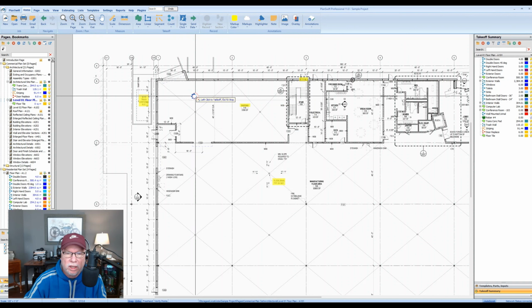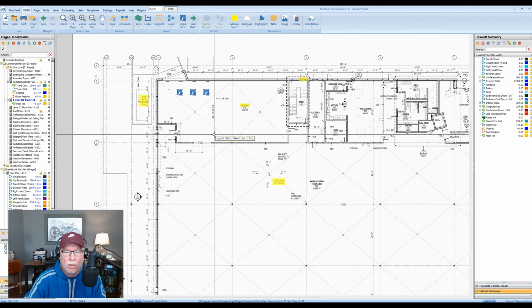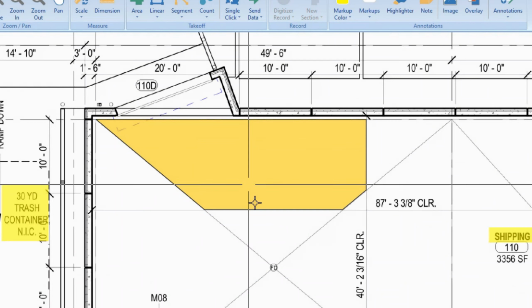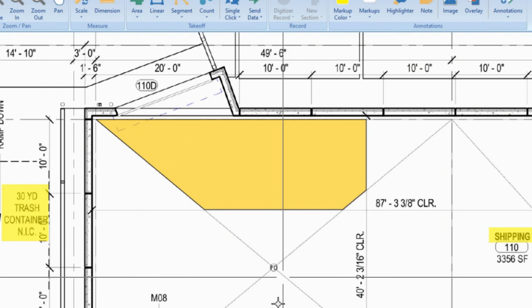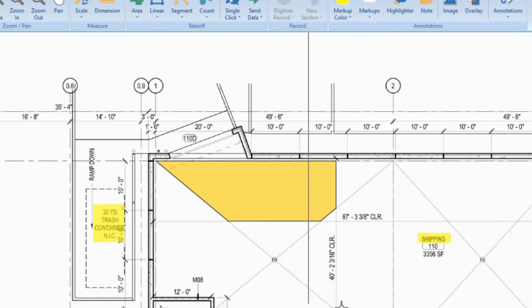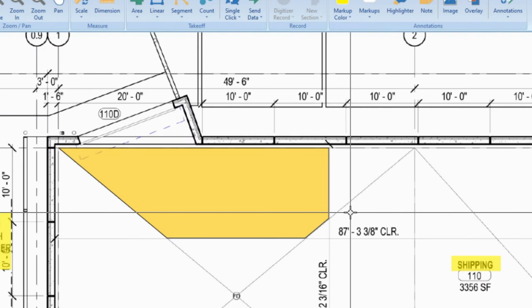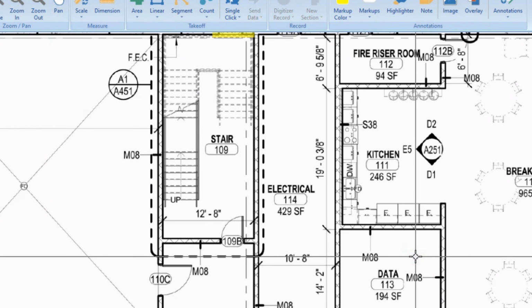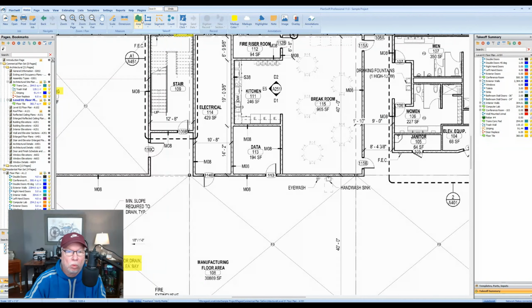And so I need to click in an area. And you can see the problem right away. Because there are additional lines, it's not really open. If I hit escape, that's what it did. Because it can't discern these lines being the actual total area versus something else in the drawing. If you get something that's truly a closed box with no other lines in it, it'll work.